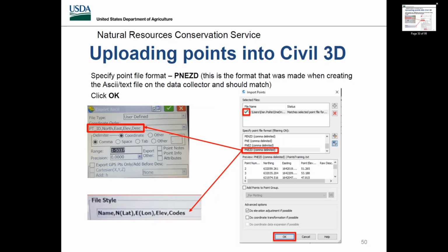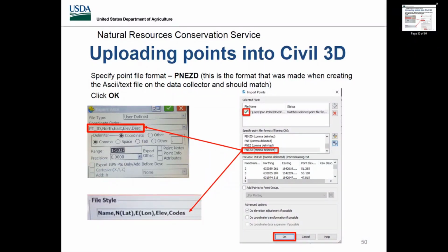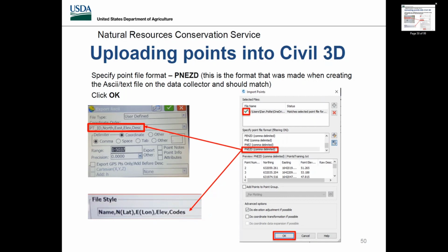We just updated our rovers through DeCarlo, and now most of our shots are pretty much on point regarding the elevations with LiDAR. Now, one thing I can say is you've got to use LiDAR loosely, and at some point you do have to do some type of field verification. If you go out to a site and you're on a specific contour with LiDAR and you're shooting it, and it's 3 foot off, 4 foot off, you can adjust that LiDAR by raising and lowering your LiDAR surface to match what the actual GPS elevations are. So you can adjust that. Hopefully that answers your question, Andrew.